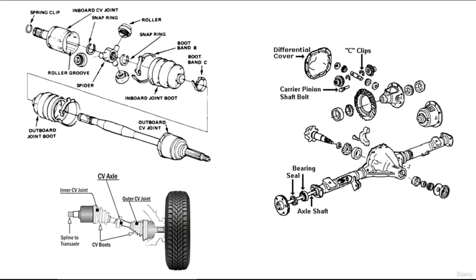The outer end of each axle has a flange mounted to it. A flange is a rim for attaching one part to another part. The flange, fitted with studs at the end of an axle, holds the wheel in place. Studs are threaded shafts resembling bolts without heads. One end of the stud is screwed or pressed into the flange. The wheel fits over the studs, and a nut, called the lug nut, is tightened over the open end of the stud. This holds the wheel in place.